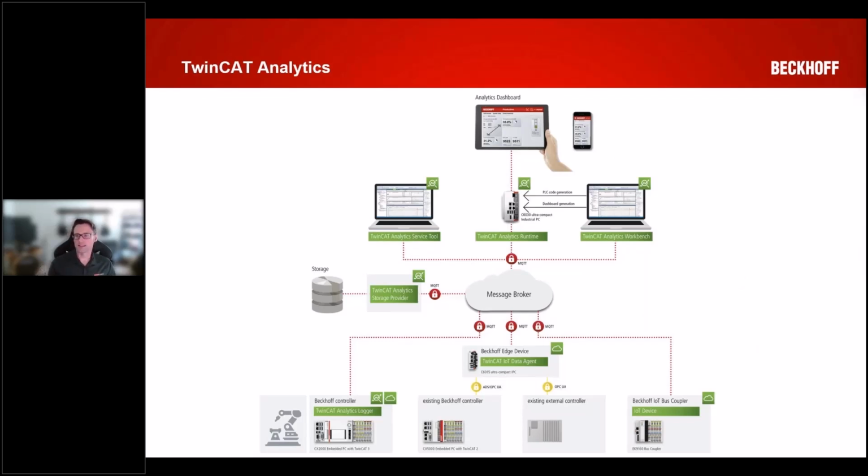Got one here. For a standalone machine, if the data gets saved locally in the IPC, is there any sort of purge service to prevent taking up the space from the hard drive? Also, really good question. The typical approach here, there's two really, is you can log in perpetuity, but obviously you're going to run out of disk space eventually. So the typical strategy there and the easiest one to configure is just a ring buffer.